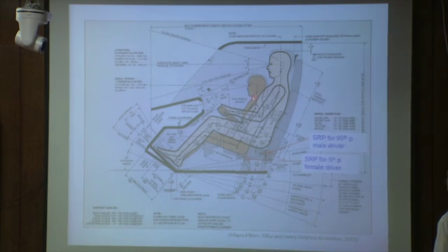Similarly, the 5th percentile female driver is adjusting the seat as per her requirement. So the seat will be moved a little bit forward and a little bit downward. That's why the SRP location has also changed from this point to a little bit forward and then downward. So this point, the seat reference point, is the 5th percentile driver selected SRP. And on both mannequins, this is the location of the H point for the 95th percentile driver, and this is the H point, meaning hip joint point, for the 5th percentile driver.